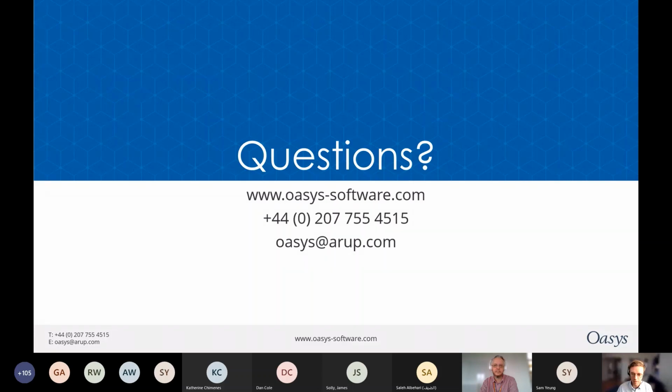And that means that when ETABS gets a Speckle plugin, you can then create your geometry with the GSA plugin, and your model, not only your geometry, but your entire model, with cross sections and loads and the geometry, and then you can stream it via Speckle and download it in ETABS.